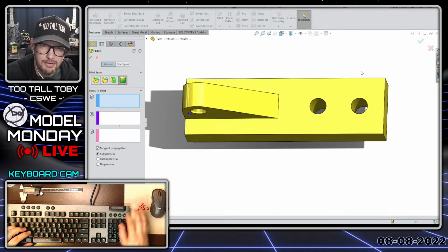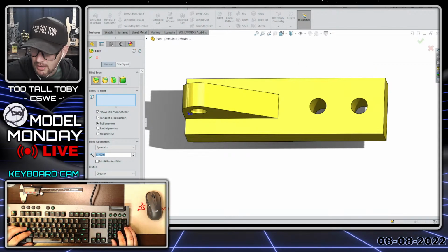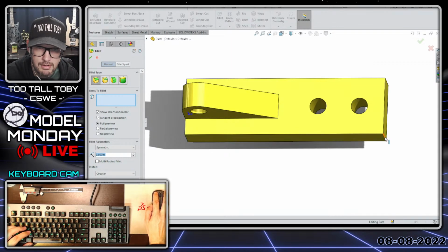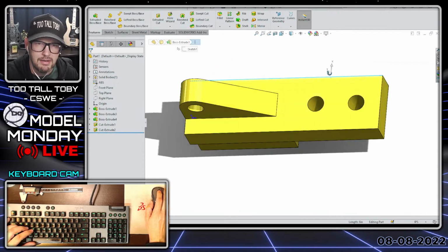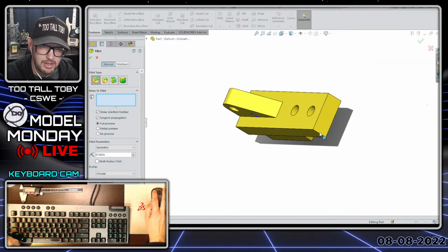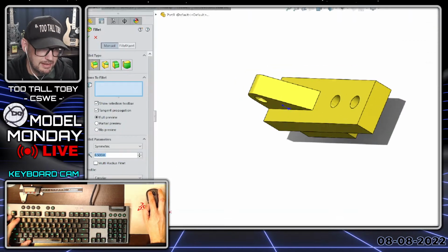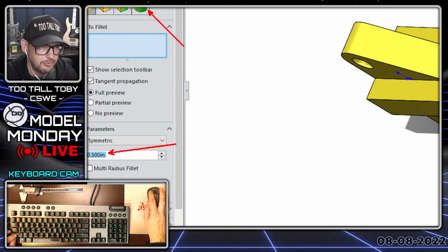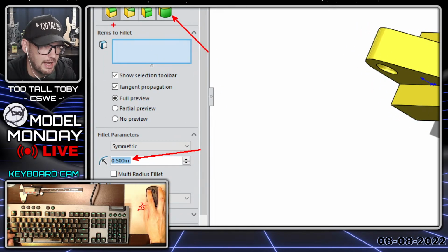and then S key, fillet, and this is going to be a constant radius fillet with a radius here of 0.5, enter, and we'll pick this edge and this edge. And so now at that point, oh, and by the way, that fillet, after you pick that second edge, usually you can just right mouse button to finish. So I can pick S key, fillet, the radius is highlighted, so the first time I was on full round, so it was a little bit funky. But usually if you start out and you're on constant here, then the radius over here is highlighted.